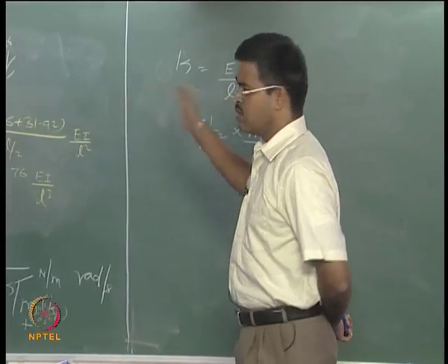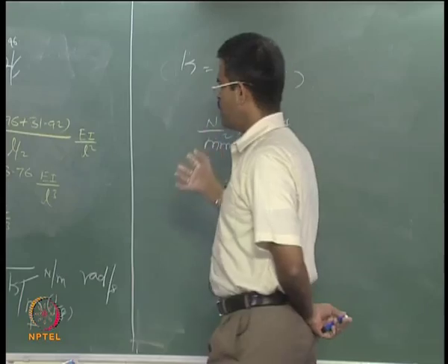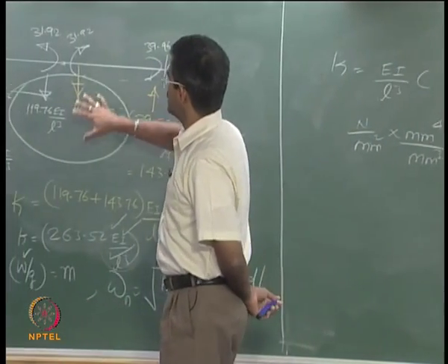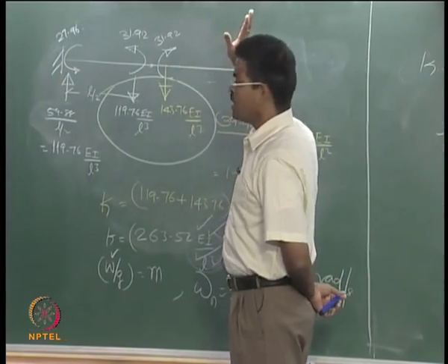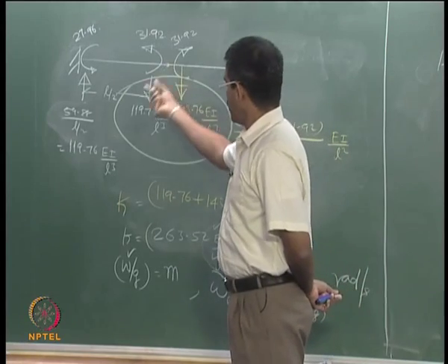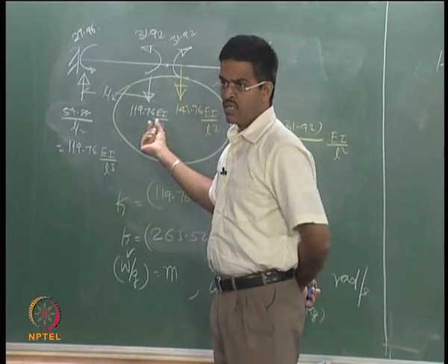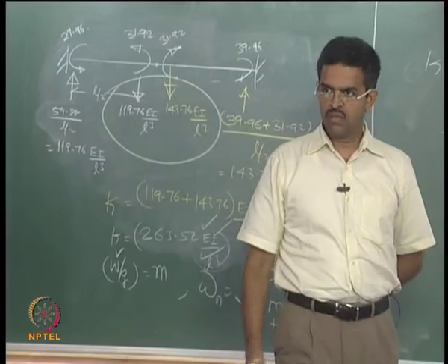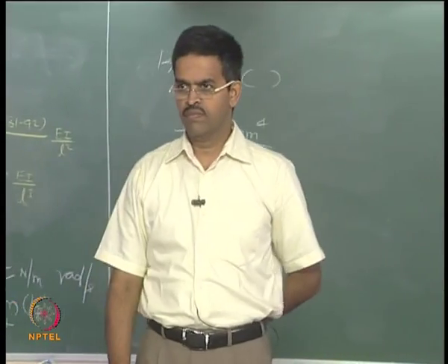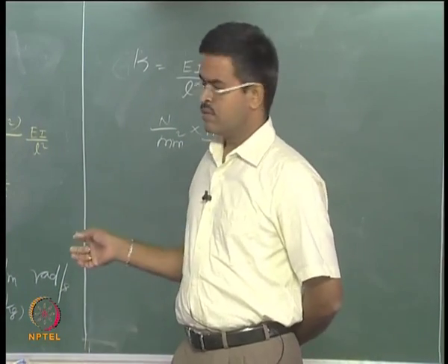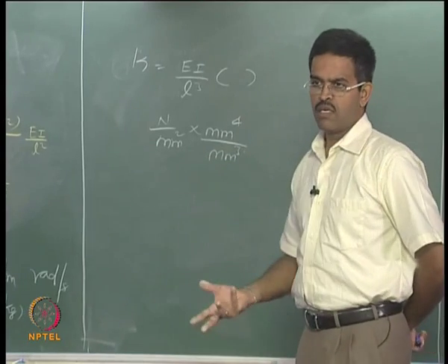Though the beam is a continuous mass system, I am assuming the mass of the beam is concentrated here, or neglect the self weight of the beam, and do the vibration analysis only for the external force acting at a specific point. Wherever it is acting, do the same argument there, get omega.